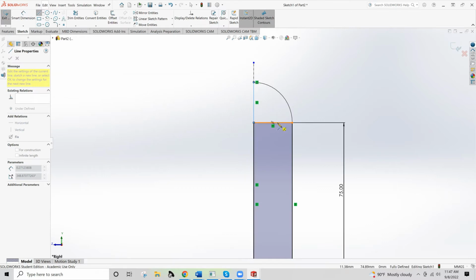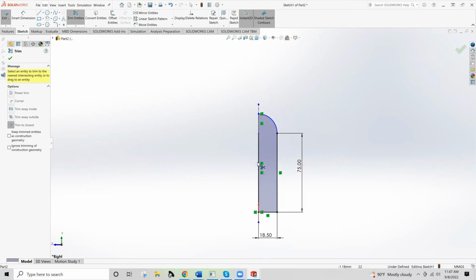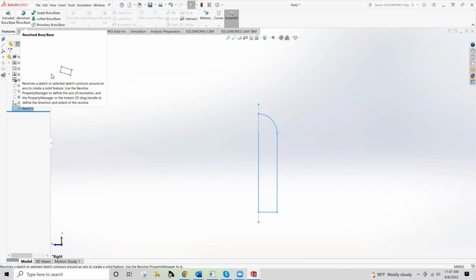Okay. Now, because of the continuous geometry that we're going to have when we're trying to do a revolve, in order to create less confusion, we're going to want to trim out a section so that we have a simple enclosed volume in order to avoid those internal geometry conflicts. Technically, this would have been the same, but I want to get you in the habit of deleting things to show that this color change tells you that you have a complete, what's called, quote, watertight 2D surface. Bunch of reasons that turns out to be helpful, but we won't go too far into that right now. That's for some later lessons.